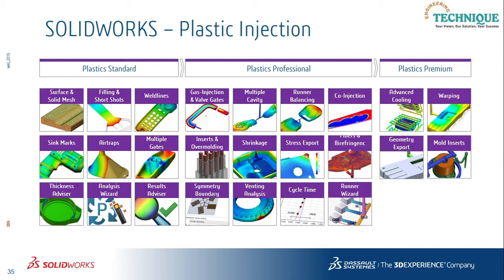Then there is a different suite for plastic injection mold, correct? So if you have components which are manufactured using injection molding, for that also there is a different suite of injection mold, in which you can do multiple cavity analysis, single cavity analysis, cooling analysis, and so on.